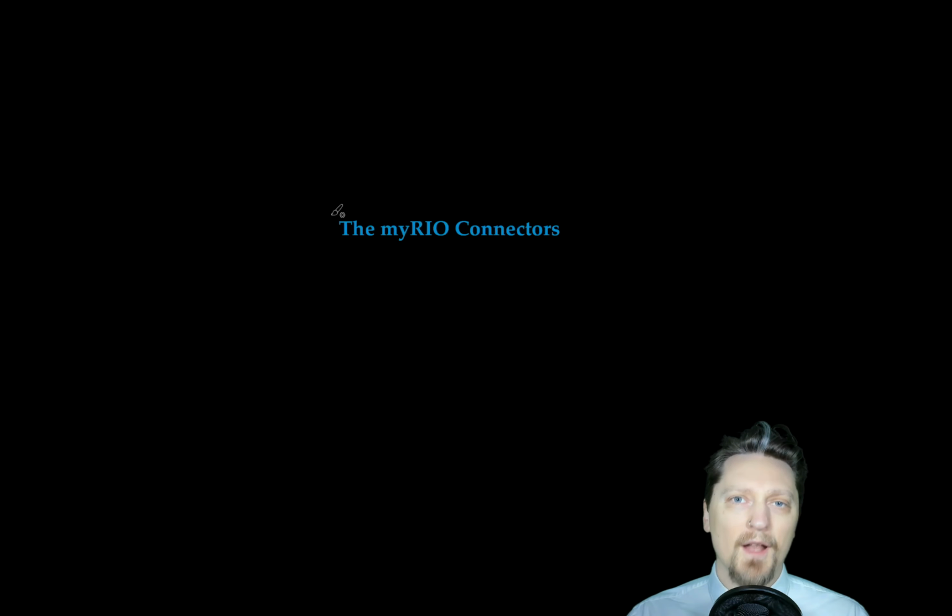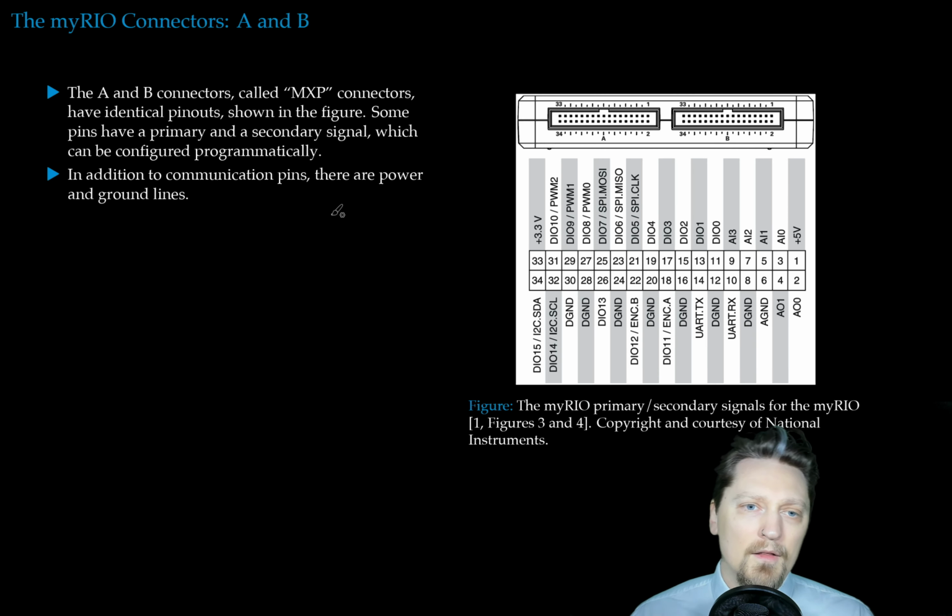The myRIO connectors. The A and B connectors, called MXP connectors by National Instruments, have identical pinouts shown in the figure. So A and B have the same pinout of 34 pins. Some pins have a primary and a secondary signal, which can be configured programmatically.